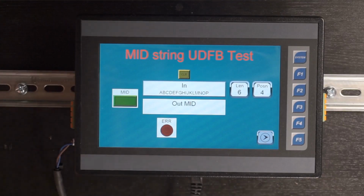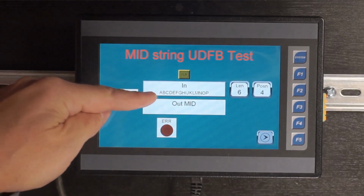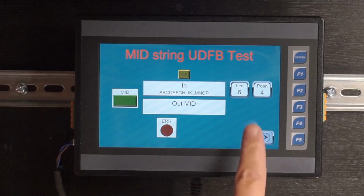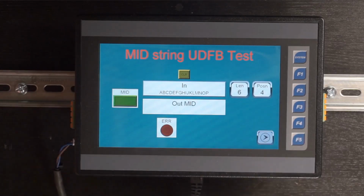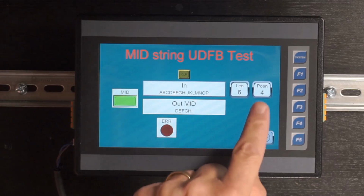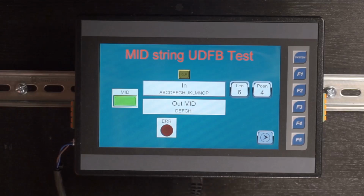Okay, so here's my incoming string. That's the input to my mid-string function block. This is my enable bit. When I turn that on, it's going to enable the function block. And I want to extract a string that is 6 characters long, starting at position 4. So when I execute that function, you can see I create a new string in my output starting at position 4. So starting at D and moving for the next 6 positions.